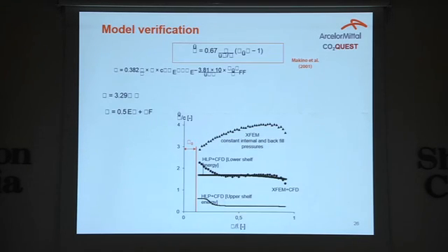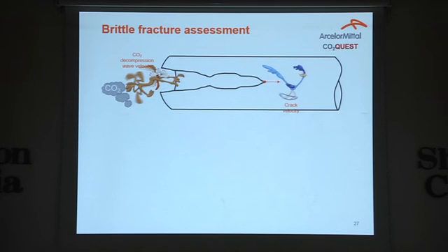Again, we compared our prediction to some analytical approaches, some sort of empirical approaches, which you see here: HLP plus CFD, which is empirical equations that we use to compare, and also XFEM plus CFD. And you see here the XFEM plus CFD are in line with the prediction of the analytical approaches at low energies for brittle fractures. So this one works actually.